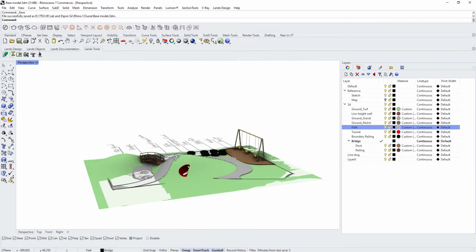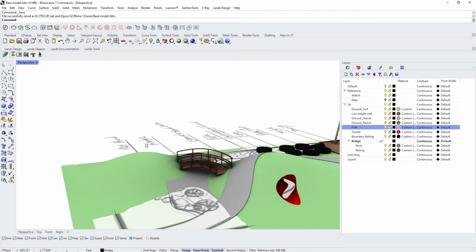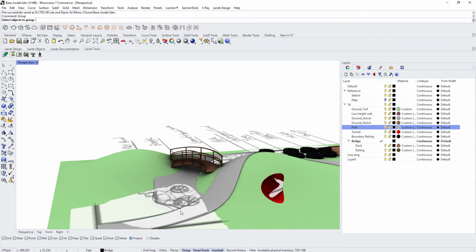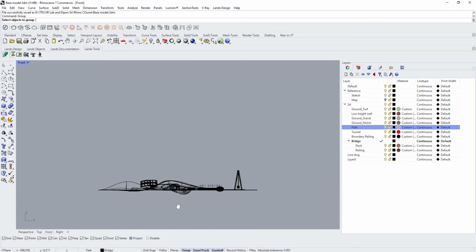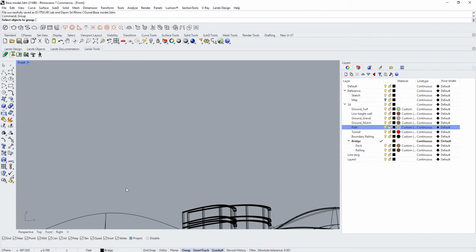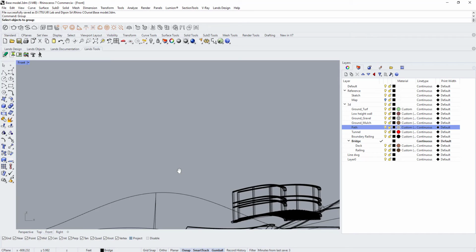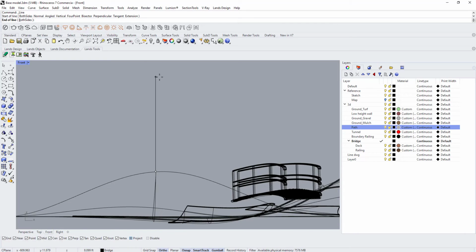Now for the last play element, I'd like to build a tipi right here, and in my experience I could not find a nice tipi from the warehouse, so I will not bother again and try to build it anyway. So in order to do that, I'll have to set the height. Let's say the overall height is 8 feet. So I'll press F8 and create an 8 feet tall line.